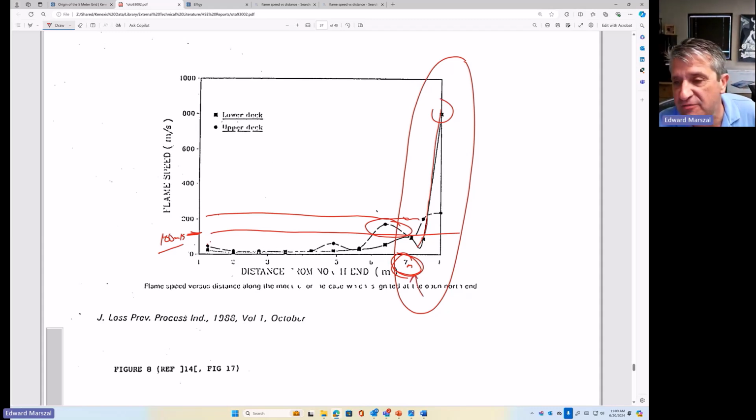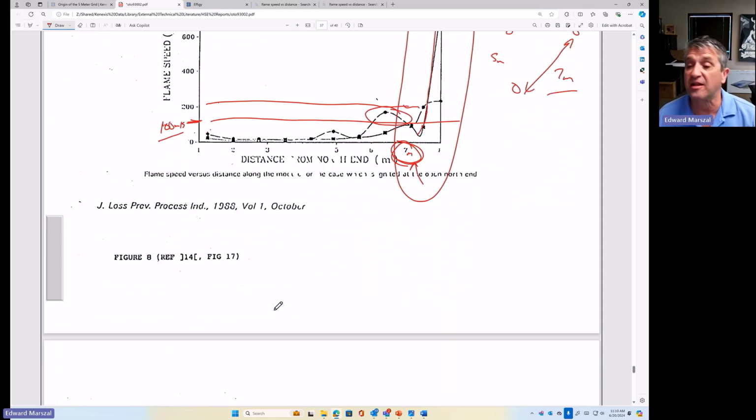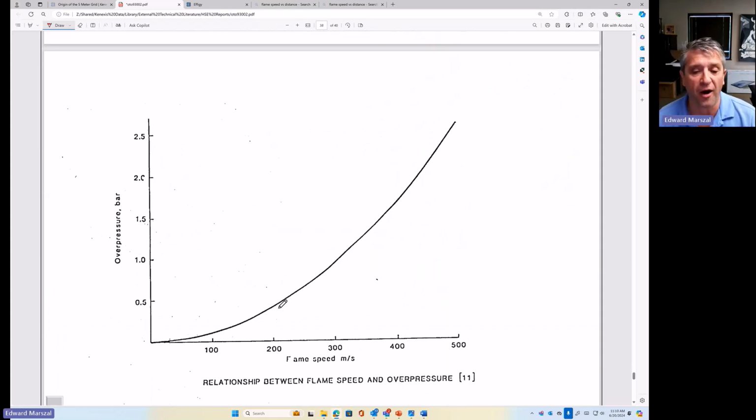And 7 meters, if you remember, if I have my 5-meter grid, my hypotenuse is about 7 meters. So basically what you're saying is if the dirty bubble is 7 meters in diameter, then he's not going to be able to hide in this grid anywhere. Assuming the center line of the gas cloud is the same elevation where the detectors are located. If the gas cloud is above or below, all bets are off.